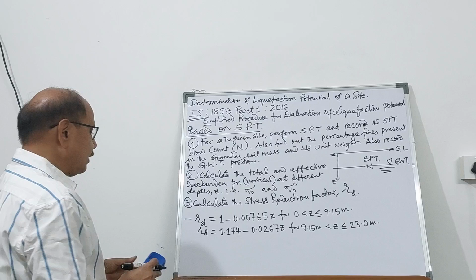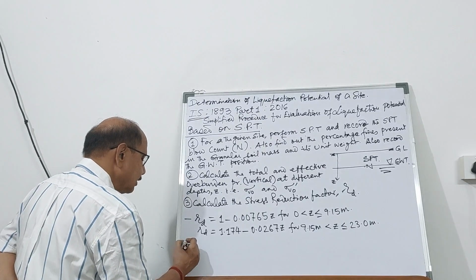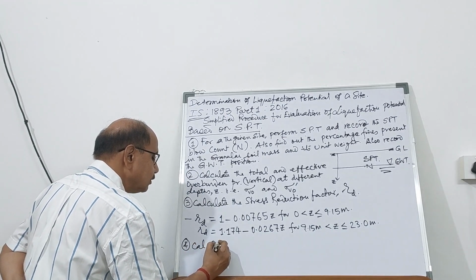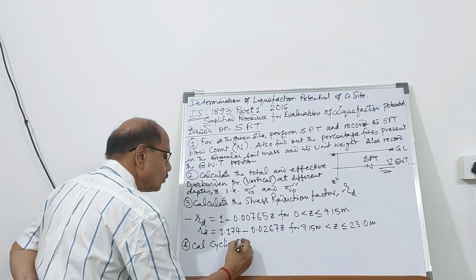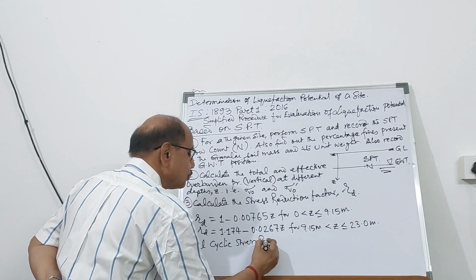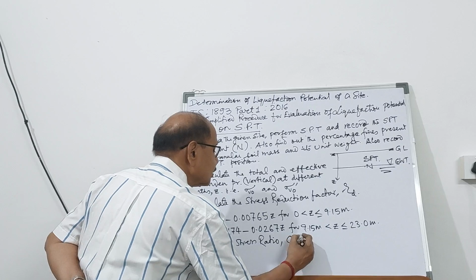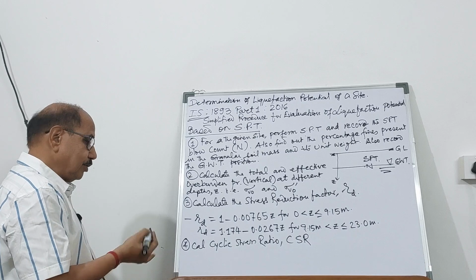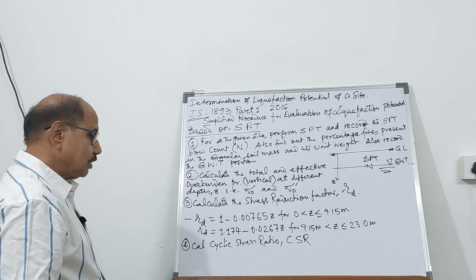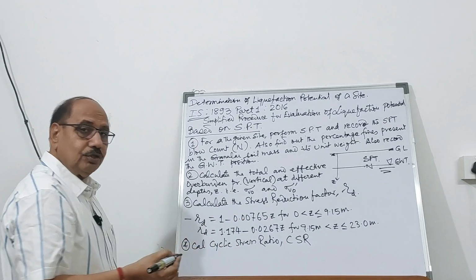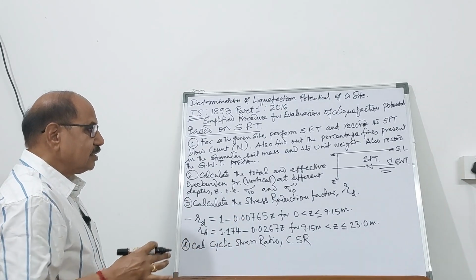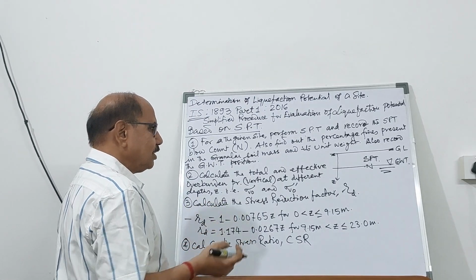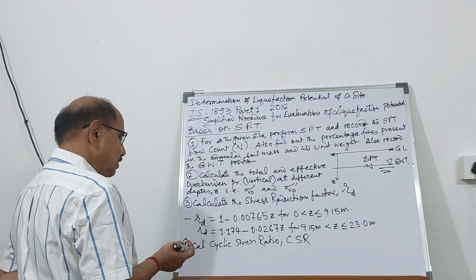Having got this, next you can calculate the cyclic stress ratio, CSR. In my last video, I have given you a complete idea about the cyclic stress ratio due to earthquake, how the cyclic stress ratio is going to develop due to the shear force or shear stresses.